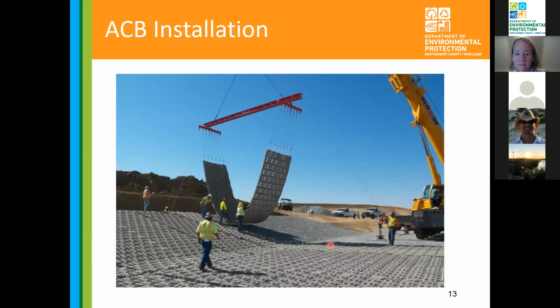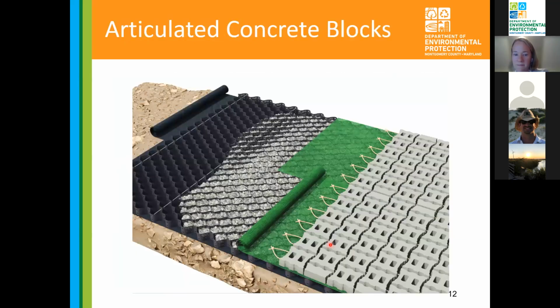So that was a couple parts, see if I remember. And I also saw a question about what's the black stuff, so I guess I'll answer that one first. I want to go back a slide. There we go. So the black roll that's separating the brown from the other black, that's just a geotextile layer, basically a filter fabric that's going to provide some separation between the dirt and the rock.